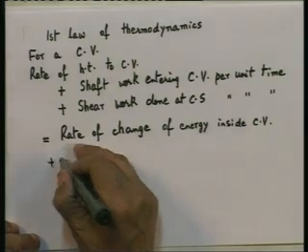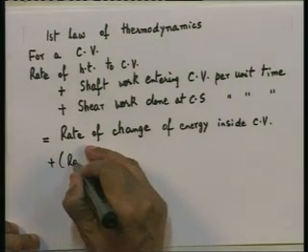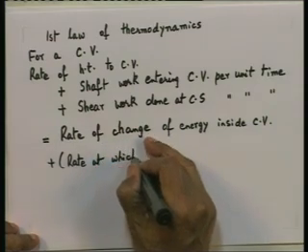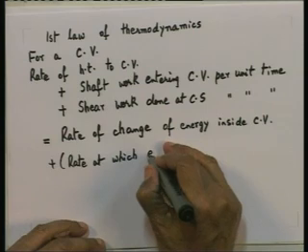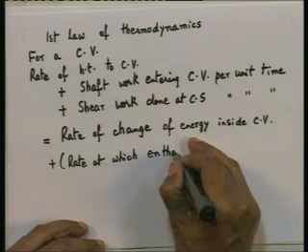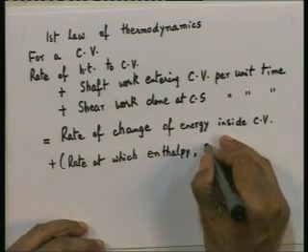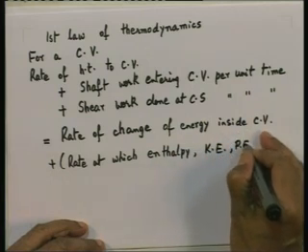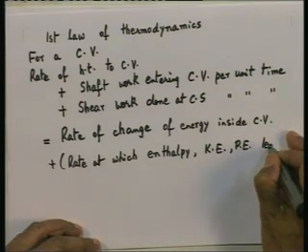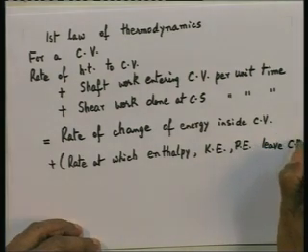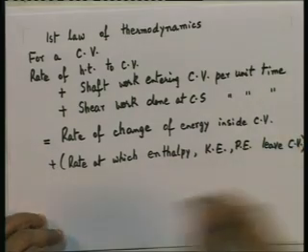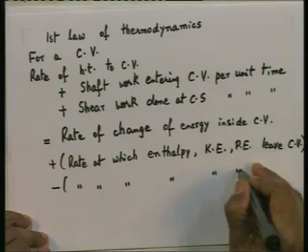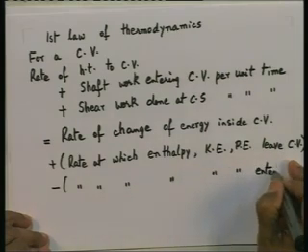plus the rate at which enthalpy, kinetic energy and potential energy leave the control volume, minus the rate at which the same quantities enter the control volume.